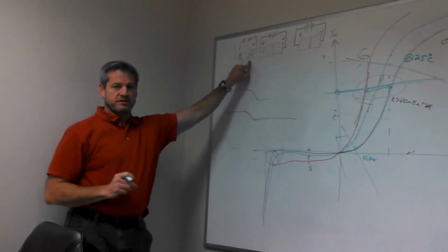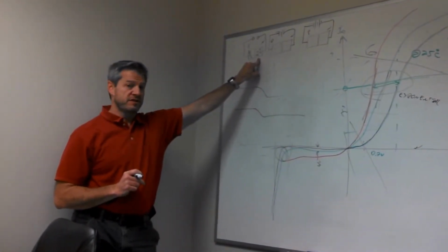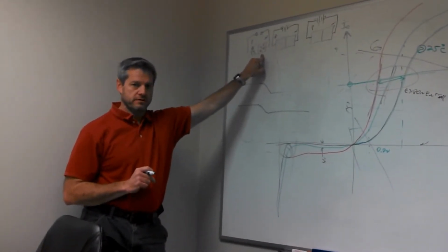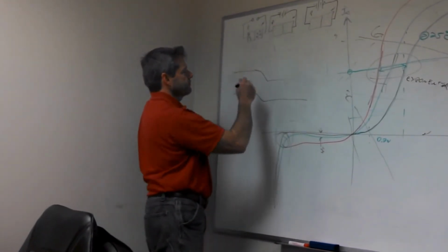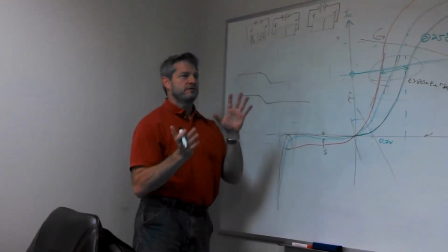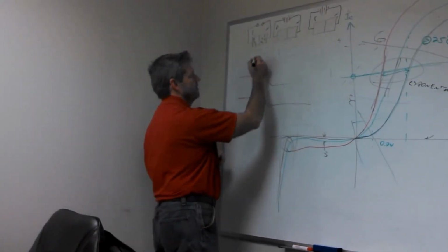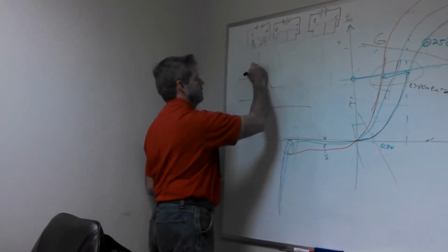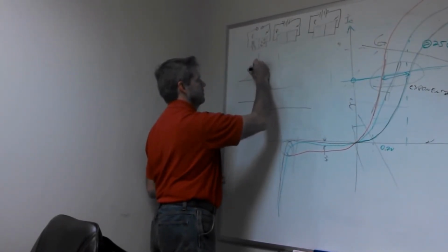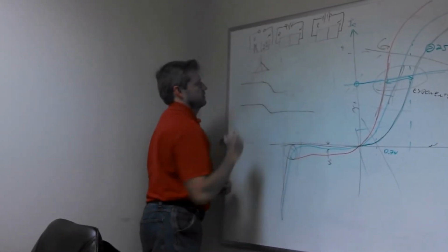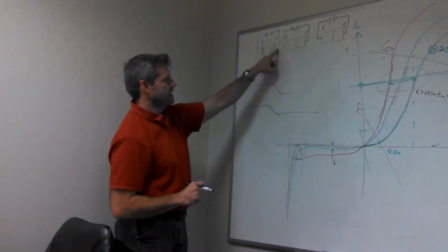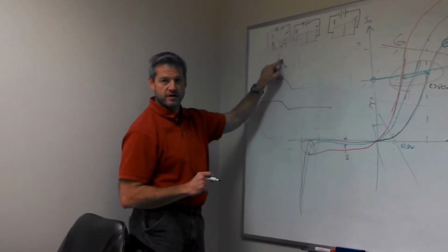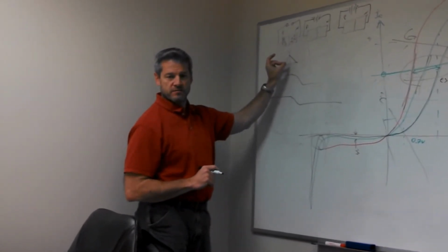It doesn't matter what the doping concentrations are. They don't have to be the exact same amount. You can have a non-uniform diffusion region. So here's the center. If I look at the diffusion lengths, if you will, if they're perfectly doped, I'm going to have a curve that looks like this. I've got ends. These electrons are going to come over here. These holes are going to come over here, and this is going to be neutral in the middle.